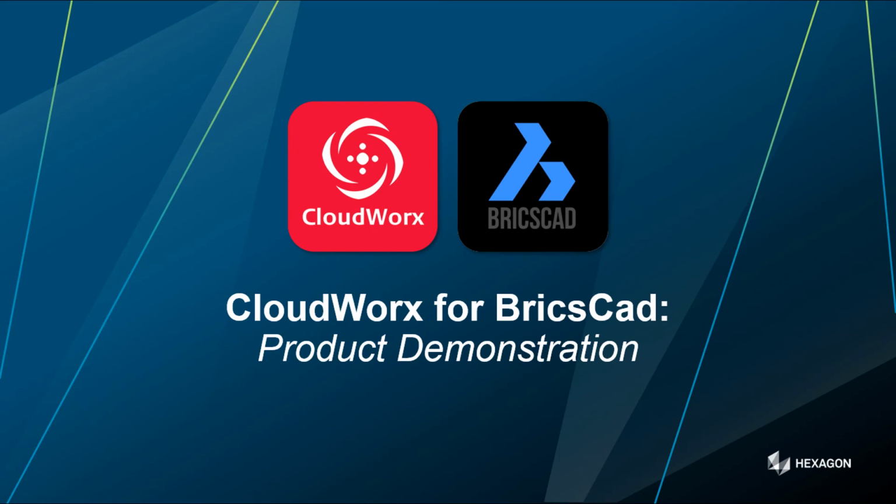So thank you for listening to that CloudWorx for Bricscad product demonstration. Hopefully you can see that we've gone through the whole process of importing the point cloud, creating some slices, aligning the data, doing some simple 2D extraction, and then moving into 3D modeling, and then using the bimify function within CloudWorx for Bricscad.